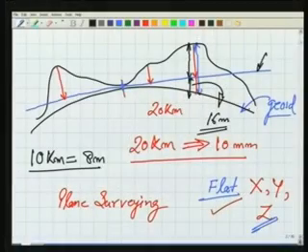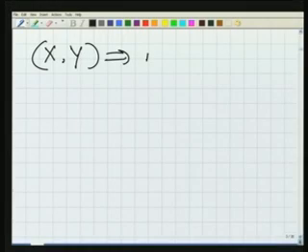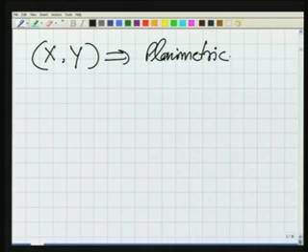So the thing which becomes clear here is that when we are measuring for an engineering project, the map in x and y, which we call a planimetric map, planimetric meaning only x and y are being plotted. If only a map is to be made which is planimetric, we can consider our earth to be flat. That means we are not measuring the curvature distances.